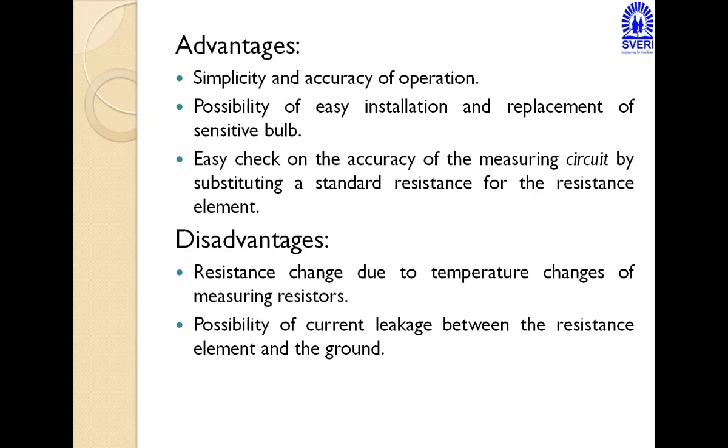And disadvantages: resistance change due to temperature changes of measuring resistors, and the possibility of current leakage between the resistance element and the ground. In this system, RTDs are not in an evacuated tube or evacuated container.